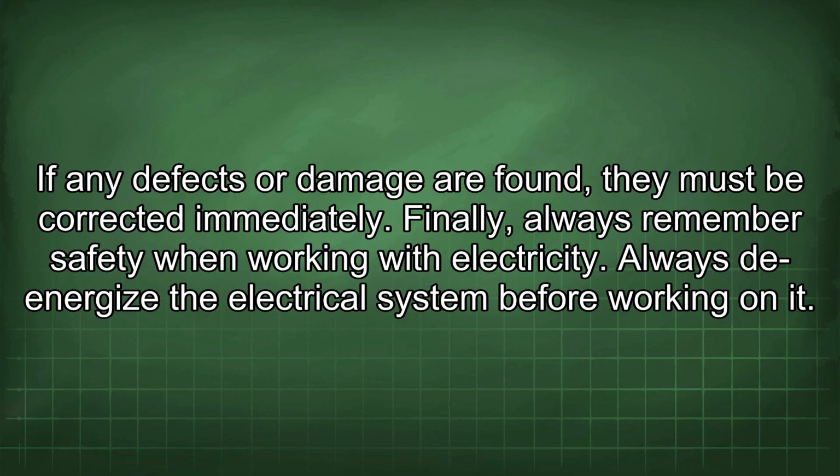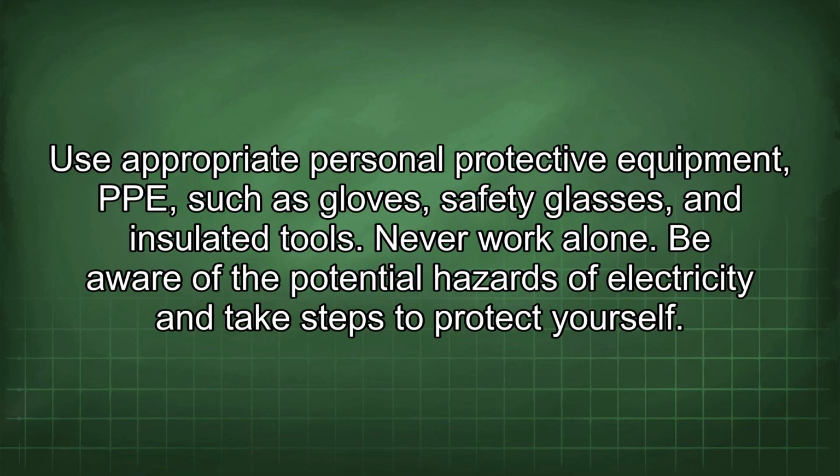Finally, always remember safety when working with electricity. Always de-energize the electrical system before working on it. Use appropriate personal protective equipment, PPE, such as gloves, safety glasses, and insulated tools. Never work alone. Be aware of the potential hazards of electricity and take steps to protect yourself.